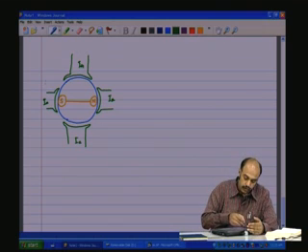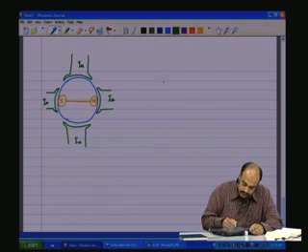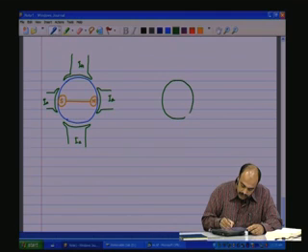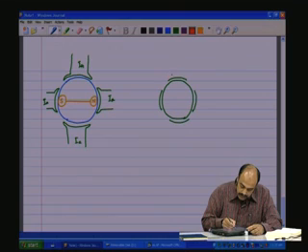And then there are 4 sets of other B phase which are tilted and shifted 120 degrees in axis, and then another 4 sets for the C phase. So they are shifted and placed in such a manner, just to indicate, so we have, let us say, the rotor. So let me say this is the A pole set, that is the A phase, and the B phase, let us say, is shifted 120 degrees.